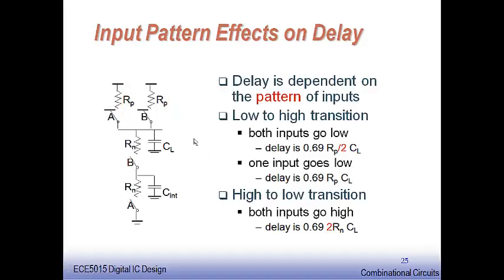Now we go to the next case, when I have a 0 for this and a 1 for this. With 0 for this PMOS device, this path would be on, and with a 1 here, this would be off. Now I have only one path, so I am going to have only Rp as the resistance, and your CL is there.